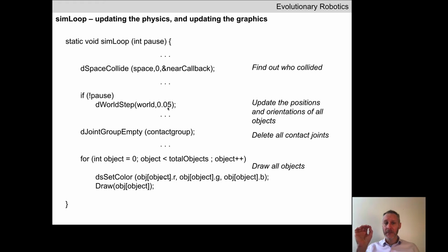Typically, or at least in the old days, you used to have to manually tune this value. PyBullet now tries to calculate this value for you automatically, so it's taken over control of this number. Why would you need to tune this number in the first place? Or why does PyBullet need to tune this number? Why not just set it to a certain value and forget about it? What happens if this value is very low or very high? What are the pros and cons of having a large time step versus the pros and cons of having a very short time step?